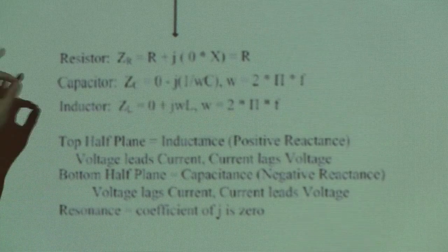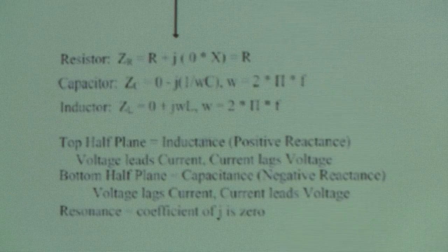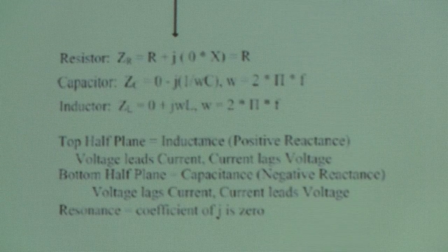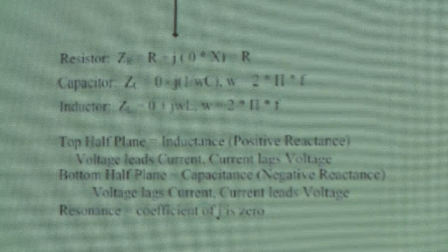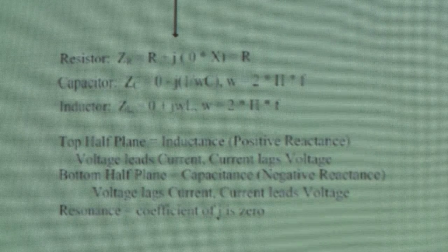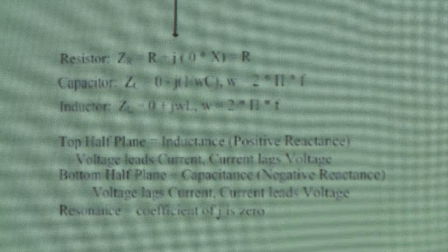So the reactance and thus the impedance of both of these guys is frequency dependent. And that's kind of what makes capacitors and inductors interesting. That's why you use them for filters. But it also makes them a little bit more complex to understand than just a resistor. A resistor is a much simpler guy.